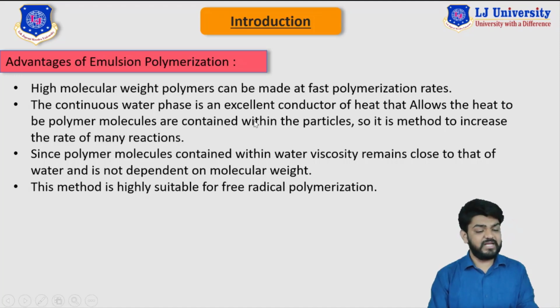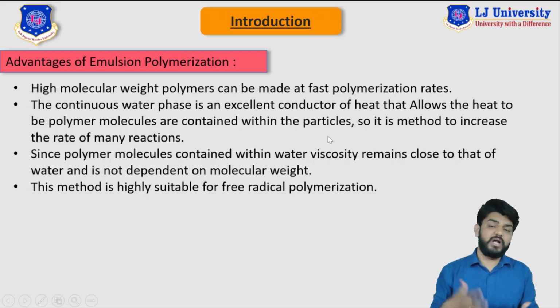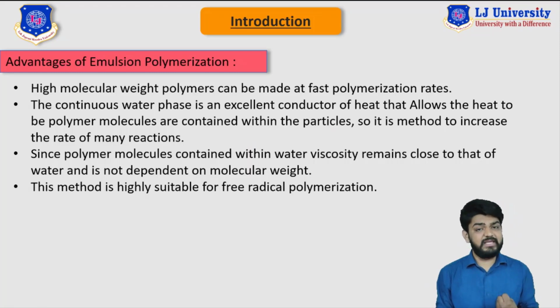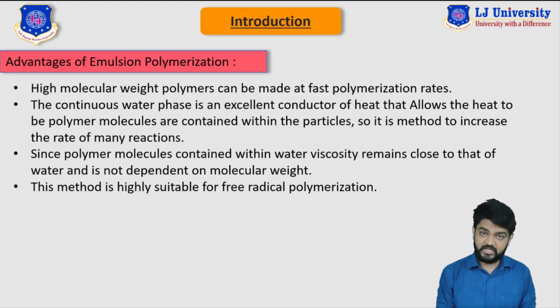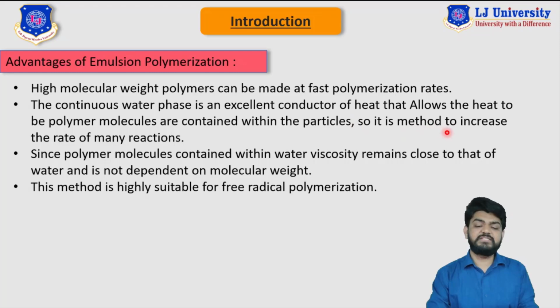The second advantage is that the continuous water phase is an excellent conductor of heat, which allows the heat to be removed while the polymer molecules are contained within the particles. So water absorbs all the heat generated in this exothermic polymerization reaction. Again, this advantage of heat transfer is achieved with water, so it is a method to increase the rate of many polymerization reactions.